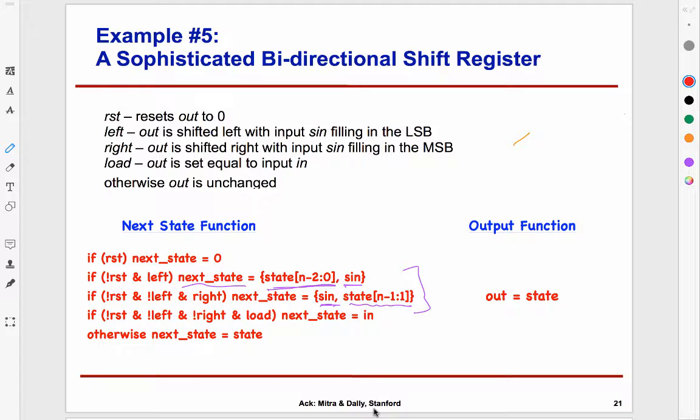FPGAs are these special kind of chips where essentially you can send them a netlist of gates, and they have lots of gates and lots of wires, and you basically send them a description of which gates and how to wire them. So essentially, think of them as programmable hardware. He'll show you a couple of simple examples, also some things that would be important for the design assignment.